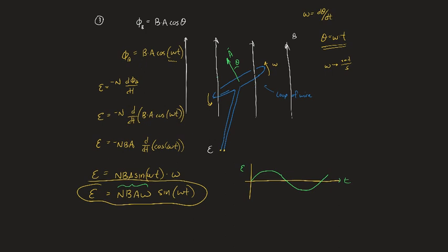It's not clear here, but do you understand that if you have an alternating voltage, you will also probably produce an alternating current? Does that make sense? Well, if you have an alternating current and you send that current into a solenoid, you understand you're going to create an alternating magnetic field. Does that make sense? Right? If the current is alternating, meaning it's getting bigger and smaller and going in two different directions, you'll generate a magnetic field that'll be going in two different directions. It'll go backwards and forwards. So you're going to generate a magnetic field this way.